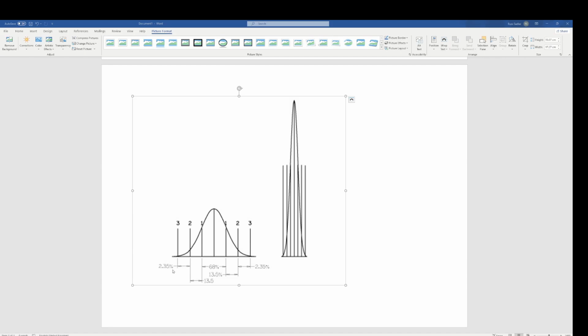Now the manufacturer of our laser tube claims that our glass tube has a beam diameter of about, say, 6 millimeters. So the baseline there is 6 millimeters. Now the height of this graph at the center represents the maximum intensity of light in the beam. Intensity of light is a very important word, intensity. The area under this graph represents the wattage, the power of your laser tube. So let's just assume that this is 60 watts. Let's call it 60 units of area.